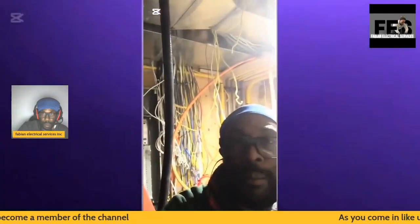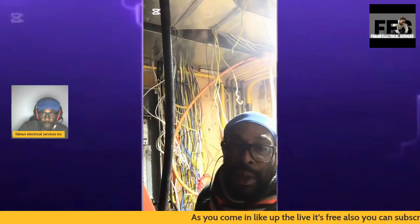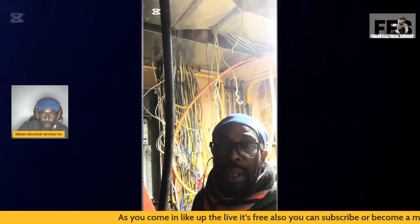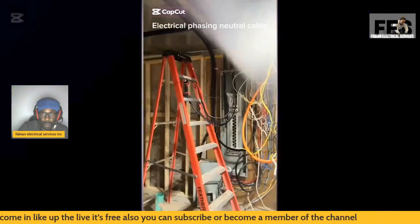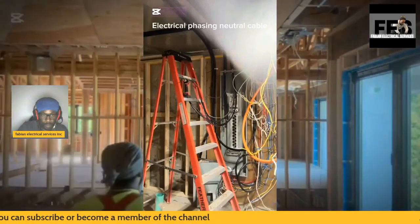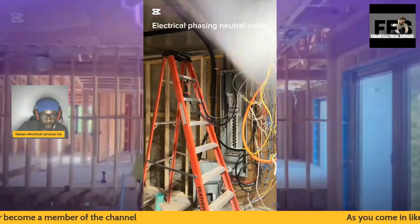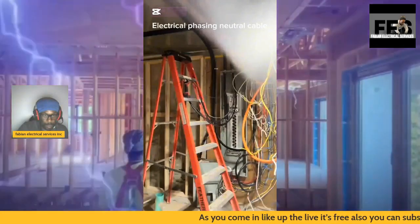The cardboard that you saw me having on top of the actual electrical breaker, the 400 amp breaker, is to protect the breaker from receiving the shavings once I start to drill. Those shavings shall not enter any part of the panel.